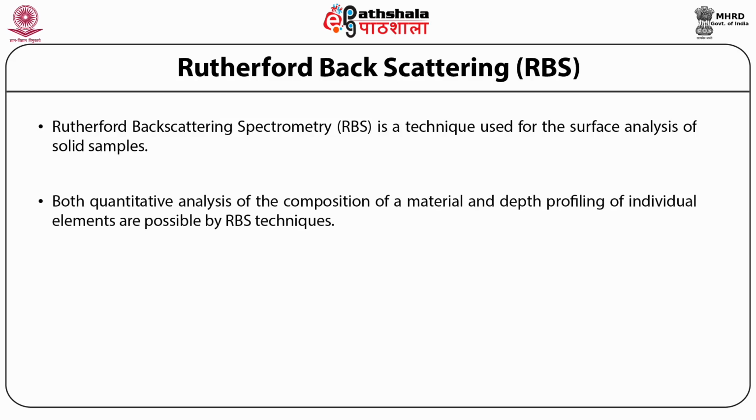Both quantitative analysis of the composition of a material and depth profiling of individual elements are possible by the RBS technique. It is non-destructive and doesn't require any reference sample for the quantitative analysis.